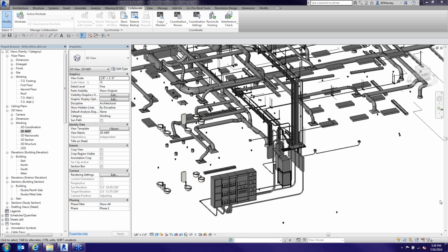One of the times I used it the most was with a manufacturer of baggage handling, box handling equipment. They would work with a lot of architects using Revit, and one of them was for an airport. In the baggage handling, we put a clearance where all the bag space needs to be clear, and it was great because once we put it in the model we realized that the bags would have taken out all the hanging light fixtures.